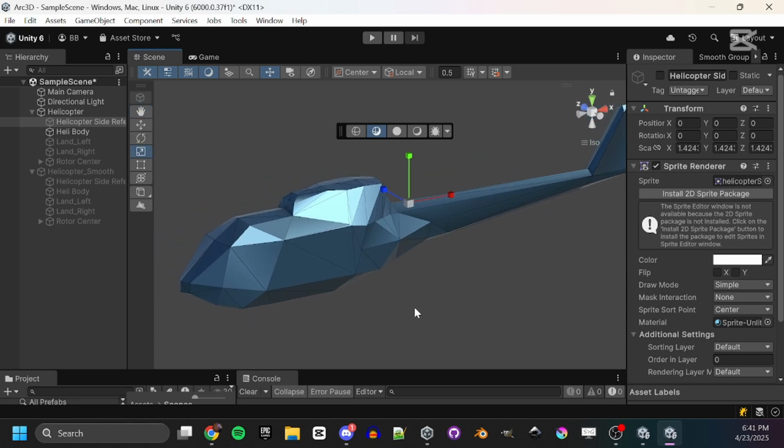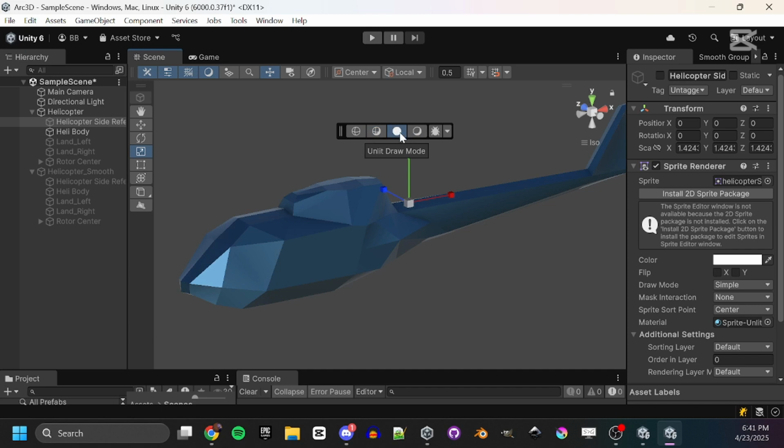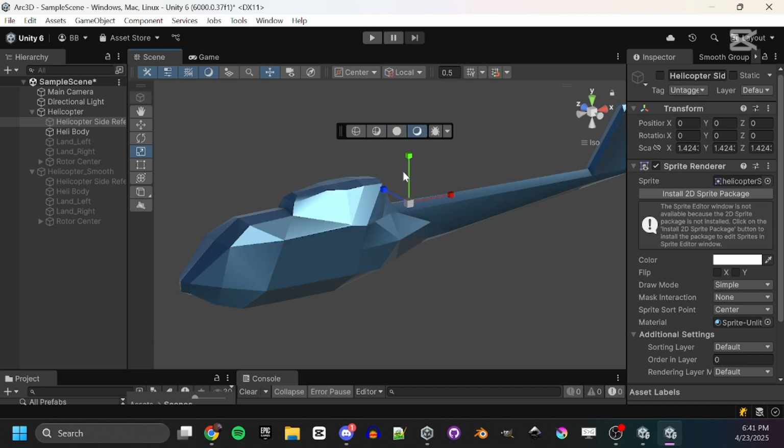So you see that things look really facety. You can see all the triangles. Granted, if I put it here in one of these shading draw modes, it looks a little better, but you're like, wow, there's still these really hard edges where things meet. Sometimes you want that, like you're making a crate, or an AT-AT from Star Wars or something like that. But sometimes you want something to look smooth.